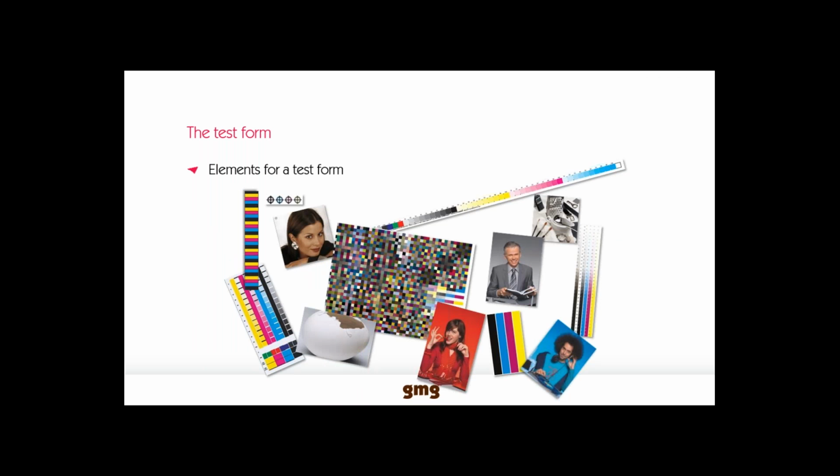The test form plays a very important role as it delivers a lot of important information about the print run and enables a quick check if the print run is really successful or not. So let's put some elements on our test form in different groups. We have some process-related elements like a print control strip for ink control during the print run.